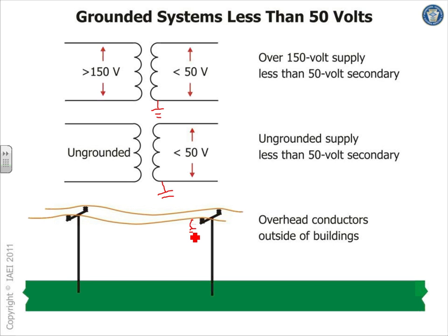Anybody know why, if we put them overhead at 50 volt, why would you use an overhead 50 volt outdoor? Cable TV? Good point. If you are to do that overhead, you have to ground it. Why do we ground it? Lightning.